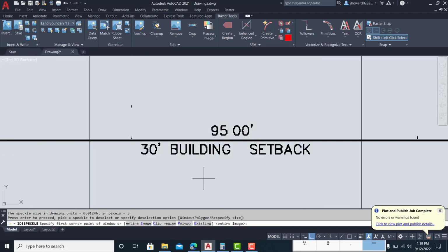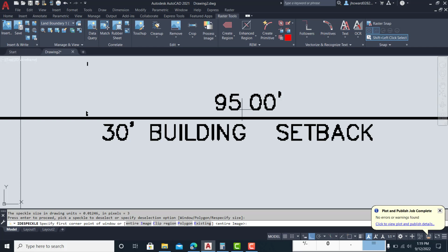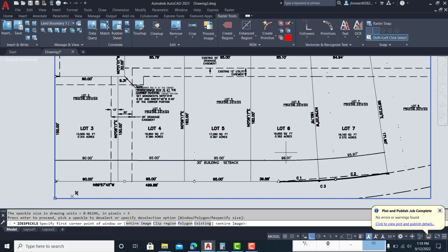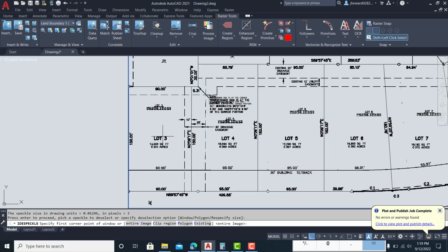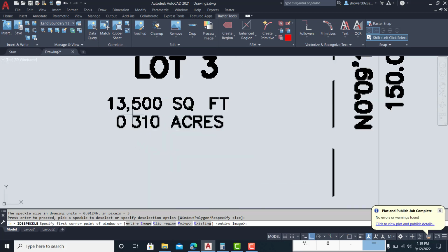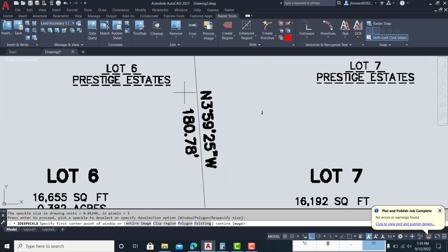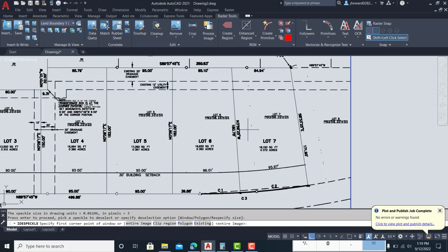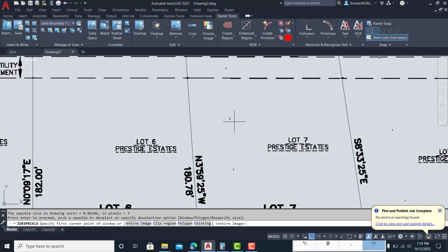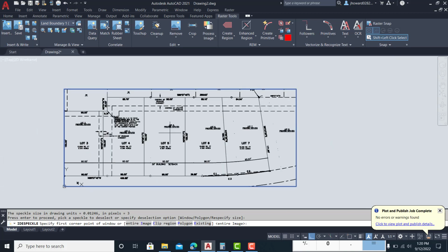But you notice what happened here. It took out one of my decimals here, or a period in a word text. So you just got to watch out and see how it takes away these things. When you're despeckling, make sure that it doesn't take out too much on you. Most of the time, that's about as good as you're going to get despeckling. Like I said, sometimes it completely covers the whole thing. And also you got to watch out for despeckling with concrete hatching and different hatches, because it will take a lot of that out.